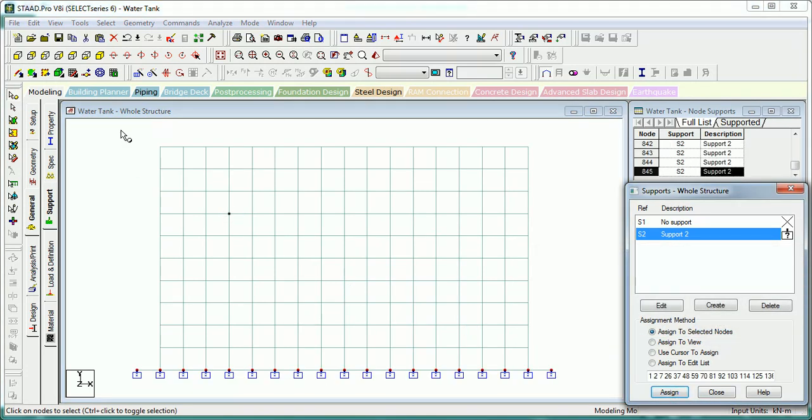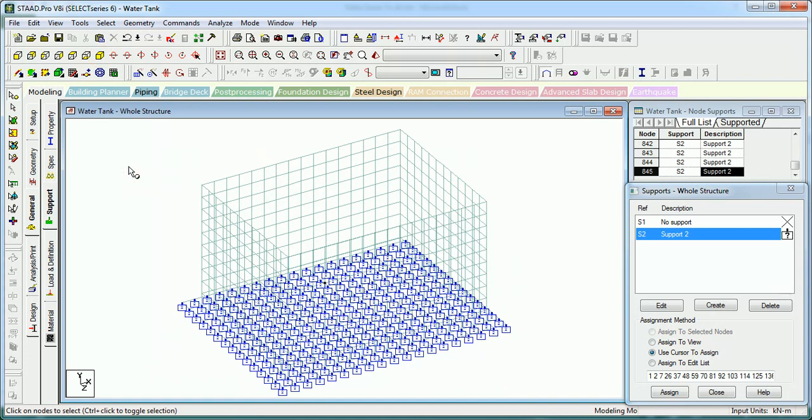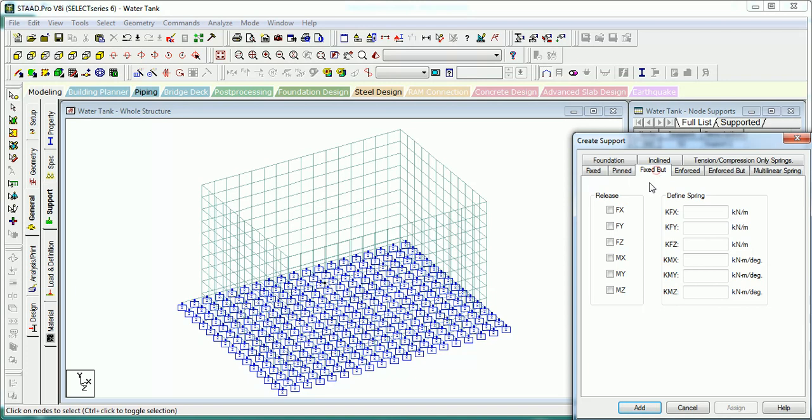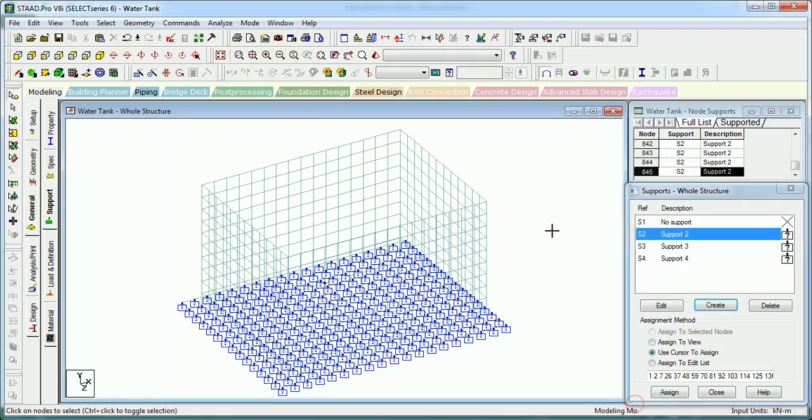Okay, now we will be transferring the horizontal force of the wall's top to the top slab, because it is pinned at the top, so we have to create a support at the top. Begin. Release everything except FX. Likewise, release everything except FZ. We will take tension only.